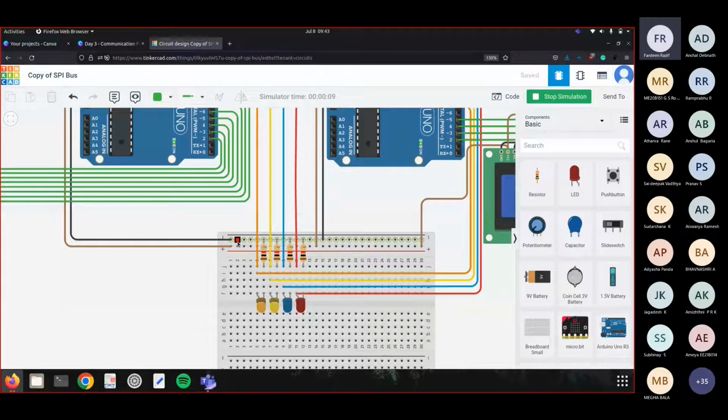We discussed that there will be 4 pins in the SPI. So which pin will that LED represent? Yeah, nice. It represents the clock pulse, because I said earlier that the clock pulse will continuously change from high to low, and that's why the LED is blinking.